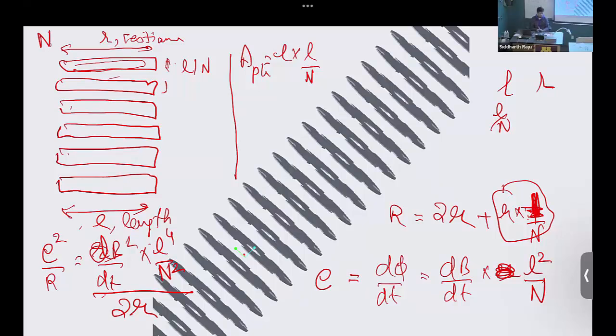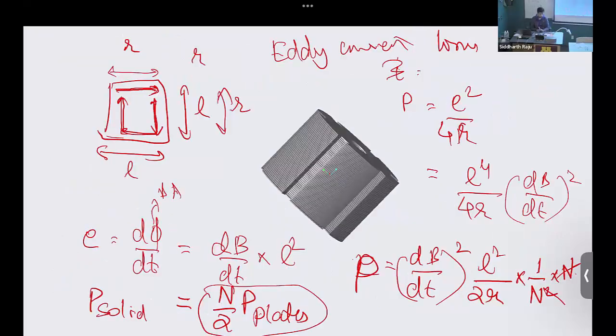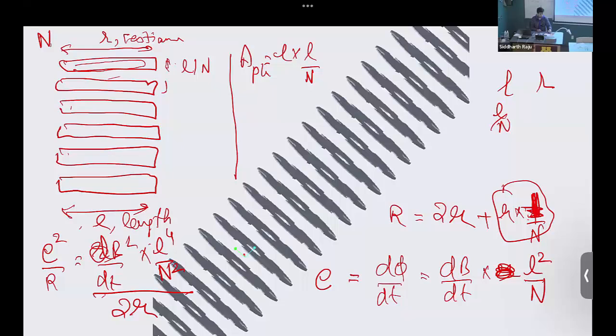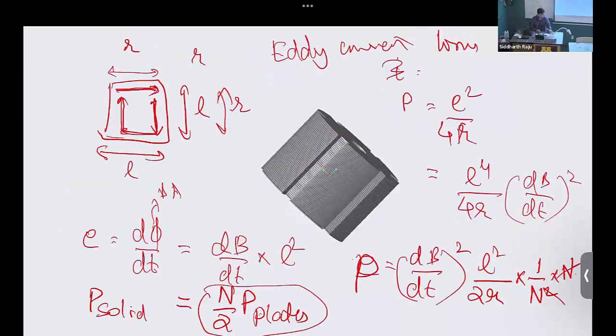Right? Any other questions? On the next slide, where you have P solid equals 1 over 2 P plates, is P plates the one on the right there? P plates is the thing that we have stacked and compressed together. Right? Whatever motor you're passing around, that has different individual plates. That is what I've shown in this diagram, where it's stacked up together as individual plates. Each of the plates is laminated, so current can't flow from one plate to the other. The one that I'm showing on the left would be the P solid. That is not the structure that we have in the hardware that we are passing around. Right? This would be the case where you get a solid iron block and just cut holes through the iron block, but not cut the plates. Right? It's just a solid iron block, so current can flow through the full face of the iron block.